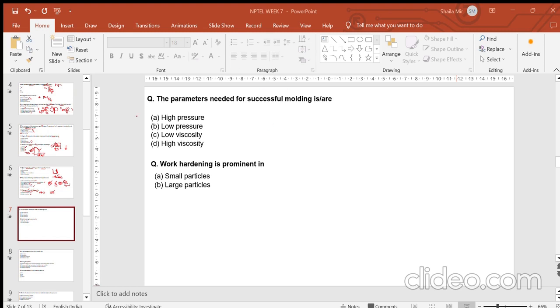The density of your compact will not be the same as the density of your pure material, because you have added certain additives. There could be another powder that you are adding, or a lubricant, binder, or any other material. The density will change based on the density of the material that you are adding and in what fraction you are adding it.